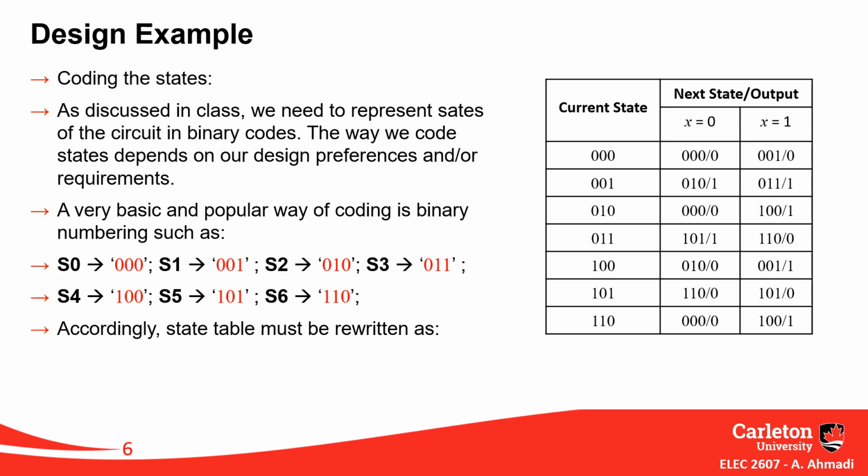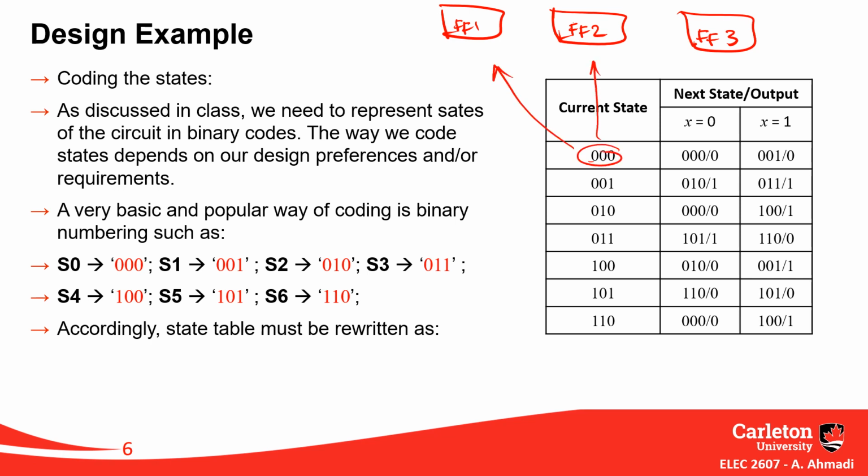Next step will be picking flip-flops, designing a circuit to save these values of states. If you are at state 000, let's say I have 3 flip-flops. Flip-flop number 1, flip-flop number 2, flip-flop number 3. This value will be saved in these 3 flip-flops. Other values as well.